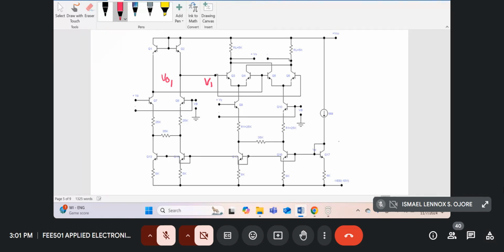Because if I just apply signal to V1, the maximum signal I can put there is plus minus 4VT, which is just plus minus 100 millivolts, 26 times 4 approximately. But by connecting this pre-distortion circuit and applying the signal as shown over there, Vx to the base of Q7 and Q8, I can get a dynamic range.